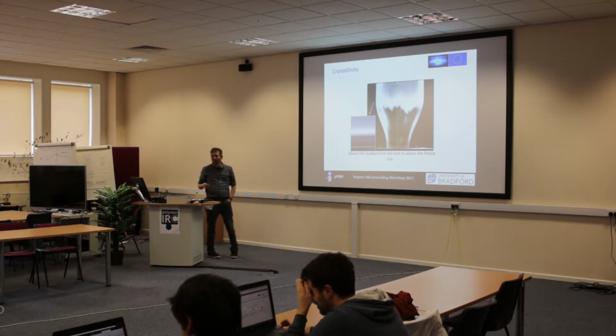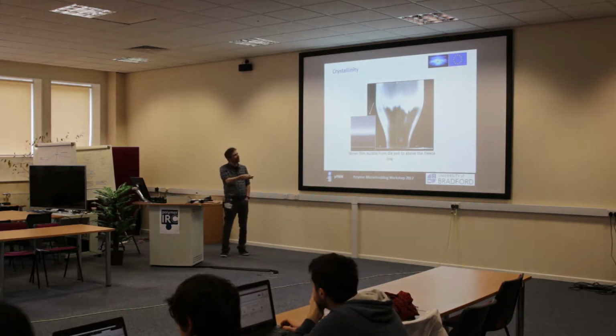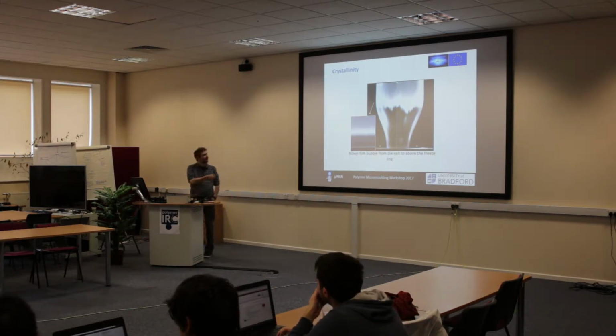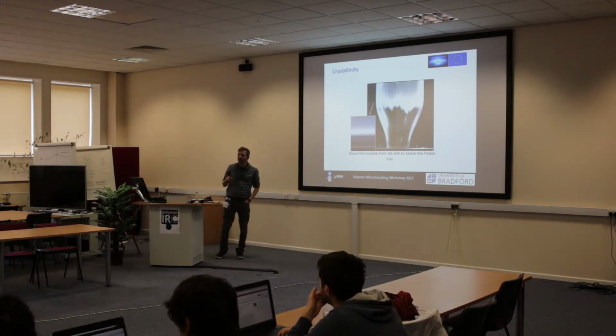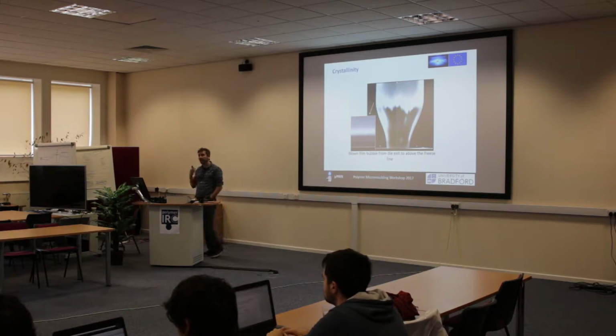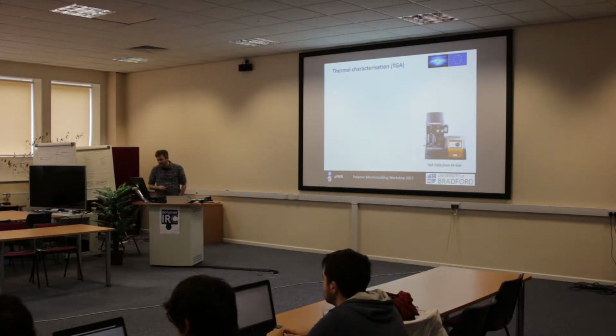So what's actually happening with the crystallization? What we're doing is cooling from maybe 200 degrees at the die down to something that hits the crystallization temperature, or the recrystallization temperature, of the material. In this case, this will be polyethylene, so that will be coming in somewhere around 120 degrees. That's when these things start to form.